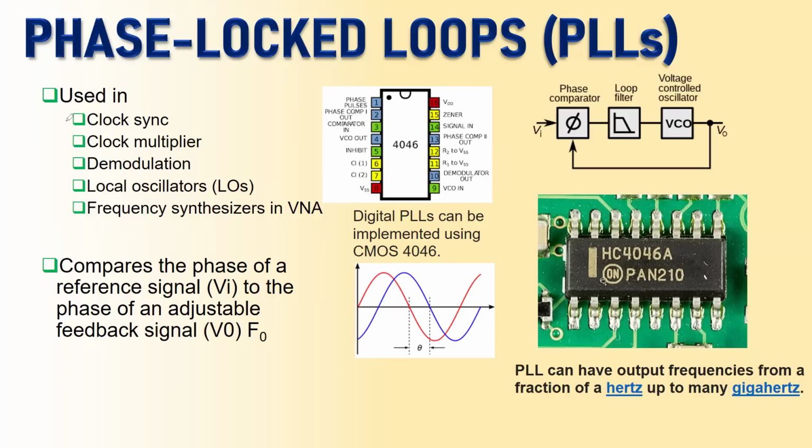So first application we would say in digital system design containing microprocessors and microcontrollers, you need a reference clock, and you have a clock that is fed to multiple digital logic inside a digital system, and there is a synchronization therefore in between the clock signals. So PLL is used for that purpose.